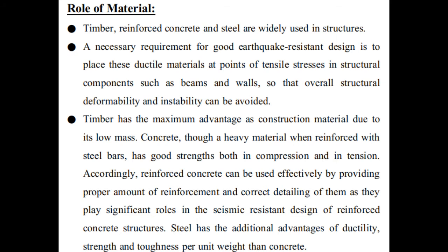Accordingly, reinforced concrete can be used effectively by providing proper amount of reinforcement and correct detailing of them, as they play significant roles in seismic resistant design of reinforced concrete structure. Steel, as I have already told, has the additional advantages of ductility, strength and toughness per unit weight than concrete.